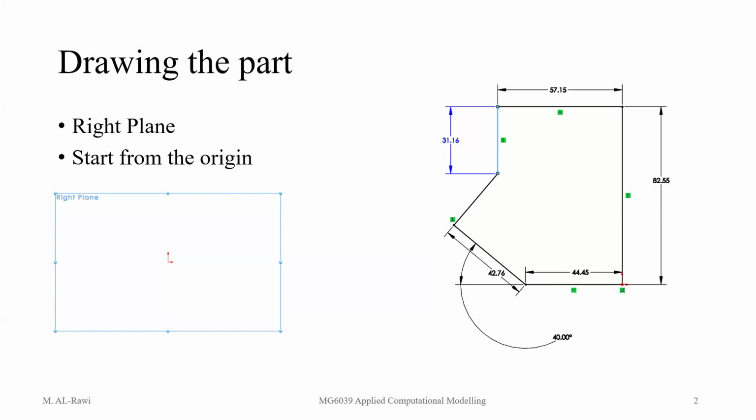When you have that situation, you can always sketch what we call a disconnected line, which is a center line. So right click on that line and go to properties, you can change it to center line. Right click on it, like you have here, and tick for construction. Now that line became a center line, which is for construction, not for drawings.